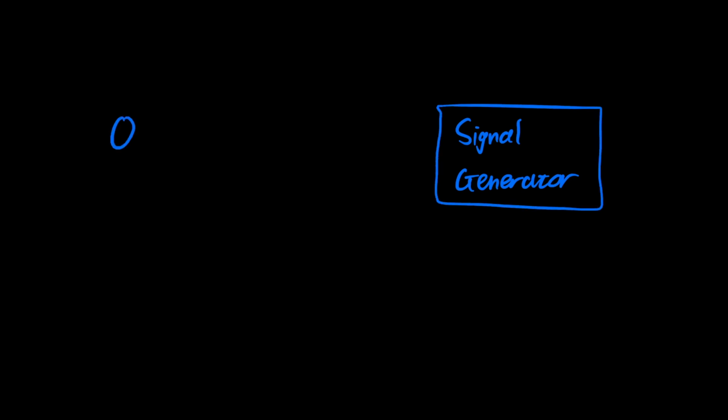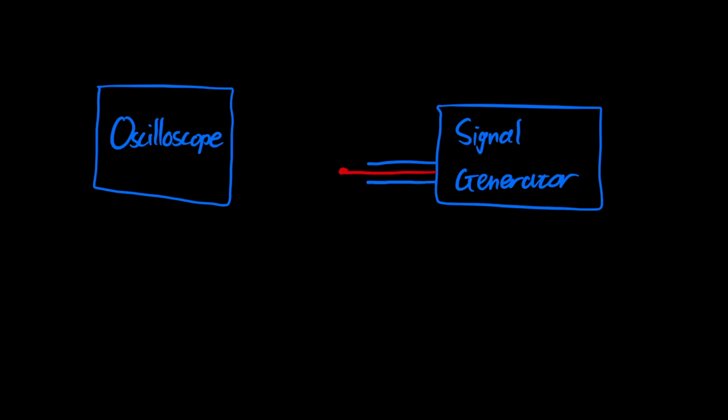The principle of transfer impedance can be demonstrated with the following simple experiment. In this experiment, a signal generator is used to produce a common mode interference current. An oscilloscope is used as a receiver system. A cable is then attached to the signal generator, converting its BNC output port to a pair of crocodile clips. This experiment does not require the negative crocodile clip, so it is left disconnected.